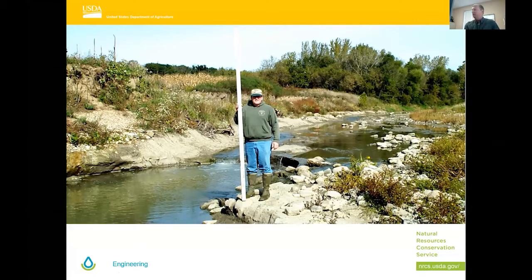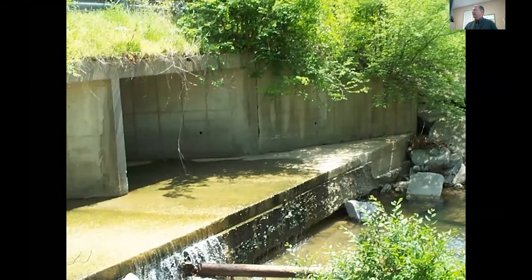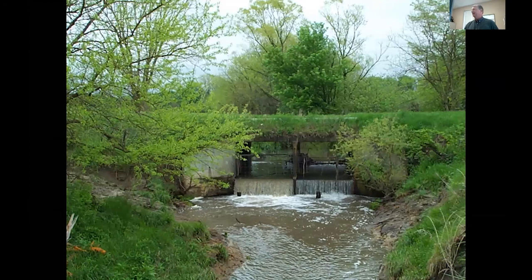You've probably seen this if you've looked at things like concrete box culverts and you see things like this at the downstream edge. You can bet that when that box culvert was installed, the floor of the box culvert was close to the actual channel grade, and now the channel itself has eroded to be nowhere near where it was. Here's another example. You see things like this fairly commonly. That's just a classic example of some down cutting that's occurred over time.